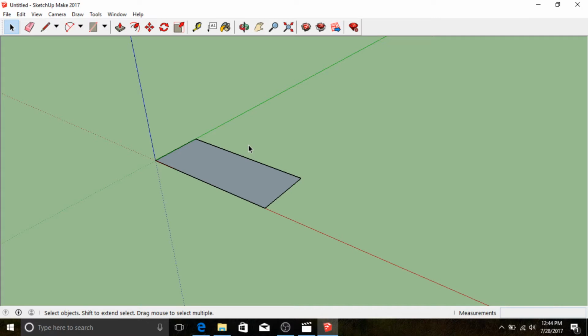And that's what I want for you folks, is I want you to be able to navigate and become comfortable with the SketchUp environment straight away. So these are three navigation tools that are super important to learn straight away. And this is why I always recommend when you're using SketchUp to use a 3-button mouse. So it's just your standard mouse with that scroll wheel in the middle that you can click.